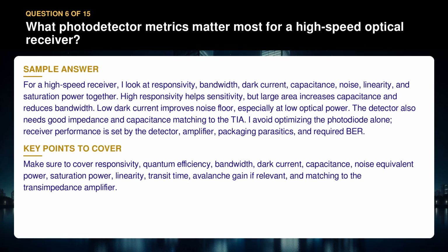Make sure to cover responsivity, quantum efficiency, bandwidth, dark current, capacitance, noise equivalent power, saturation power, linearity, transit time, avalanche gain if relevant, and matching to the transimpedance amplifier.